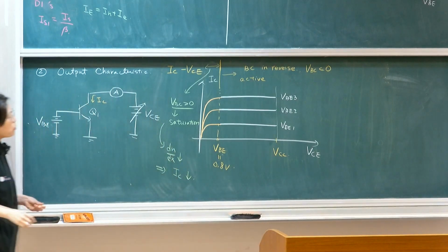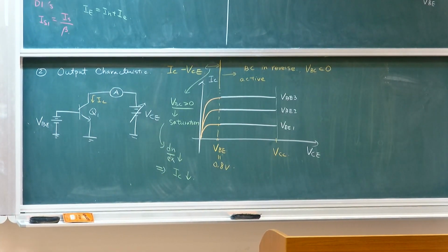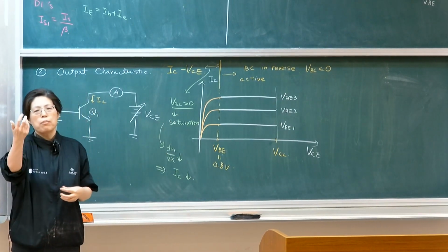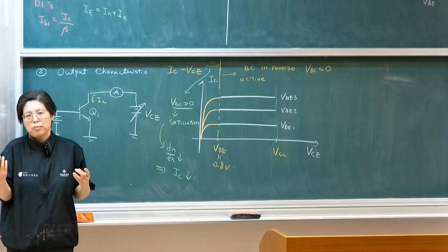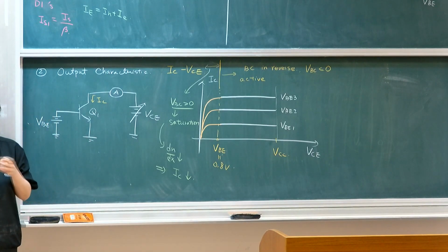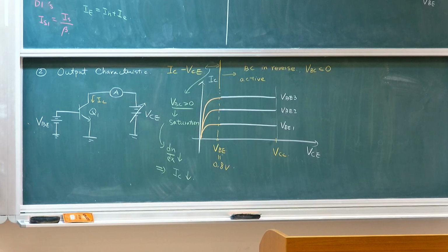As I said, there are two definitions of saturation when we actually come to discussing. One is that it's actually forward biasing, but even though they're pumping a little bit, because of the exponential factor in this term, even though it's pumping, you don't actually see it. So it does not create too much significant difference in your gradient. Only when you forward bias to a level which is comparable will I actually see the effect.